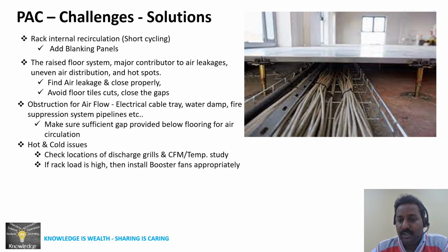So we need to check this, and increase the CFM to the loaded racks and close the tiles with hard tiles wherever the load is less or supply air is not required. And if after doing all the necessary actions we still have a hotspot issue, then we can go for installation of booster fans for the respective racks which require more supply CFM compared to other racks. So we can go for booster fan installation as well.